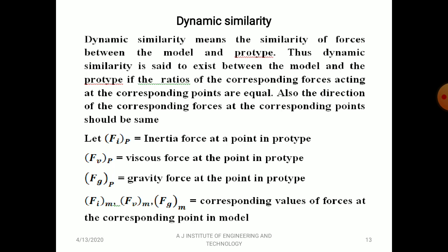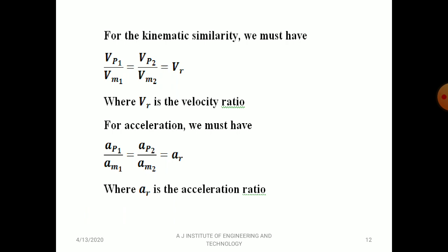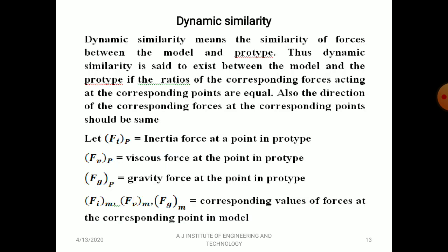For geometric similarity, the parameter is shape and size. For kinematic similarity, the motion is the parameter, that is velocity and acceleration. Now the last one, dynamic similarity, for that the force is considered.